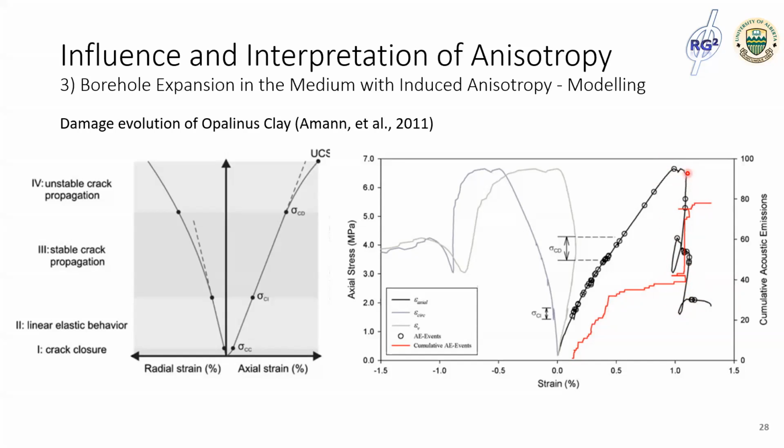Before that moment, it was just microfracture initiation and development. But at this moment, all the fractures coalesced and formed a big fracture, which is the rupture plane. After that, the post-peak behavior is dominated by the sliding of the rupture plane instead of further development of microfractures. That's why the acoustic emission signal stopped accumulating after that point.